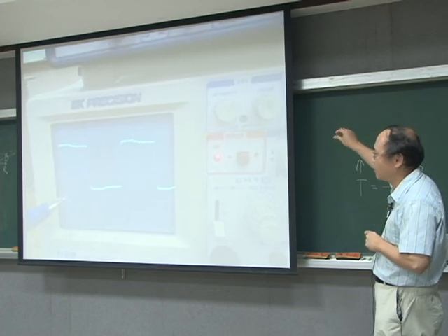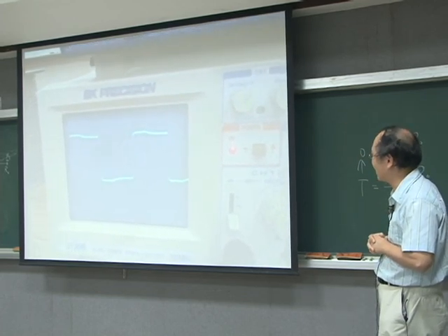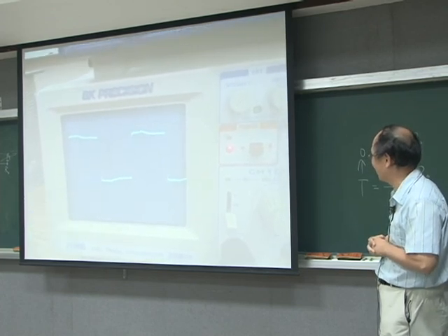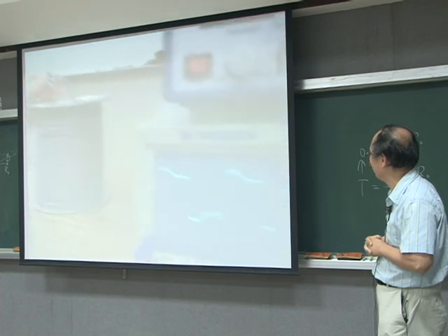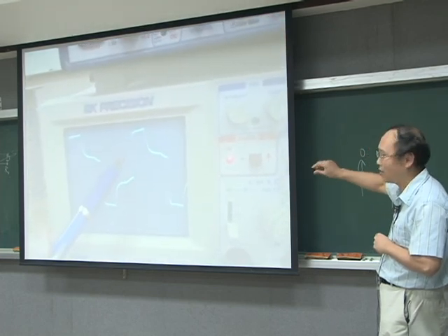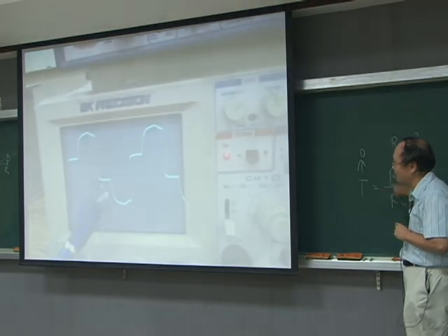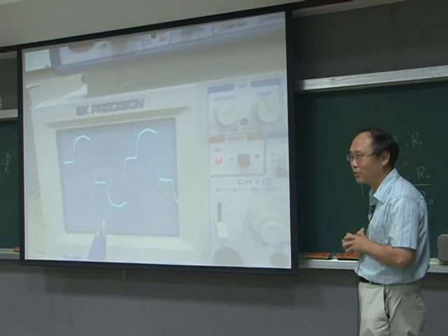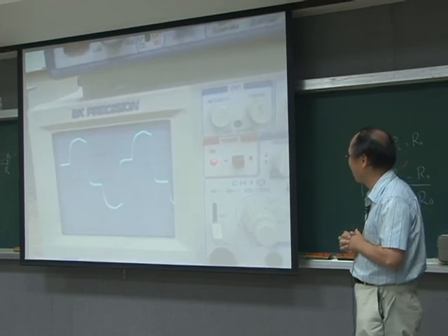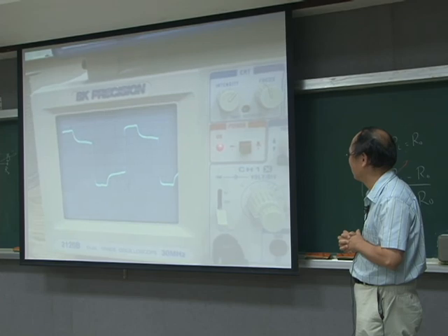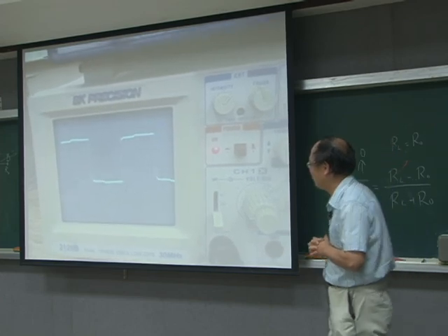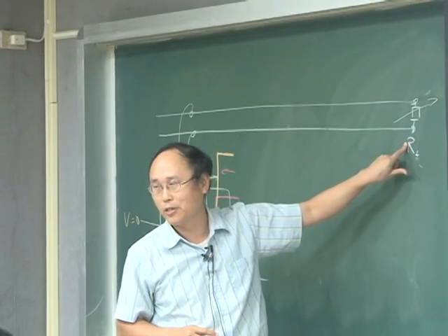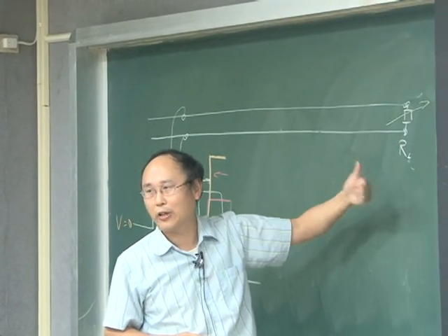And I think it's going to twist the variable resistor again, so you can see the change of the reflection. So we have to wait a little bit. Okay, it's varying this value again, so you can sort of see the reflection of the signal again. So if you can properly terminate the cable with some impedance, in fact, you can eliminate the reflection of the signal.